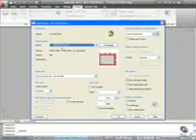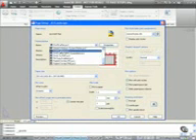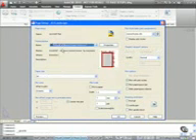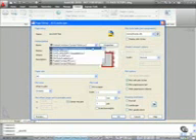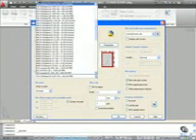We're going to make sure that we're plotting to a DWF, not an actual printer. So there's our DWF6 ePlot PC3 file. Make sure you get that. I clicked on the wrong one there, just click on the right one. It's always good to check that printer plotter name, otherwise it could go somewhere and you just don't know where it's gone. Paper size, we're going to look for an ISO A3.